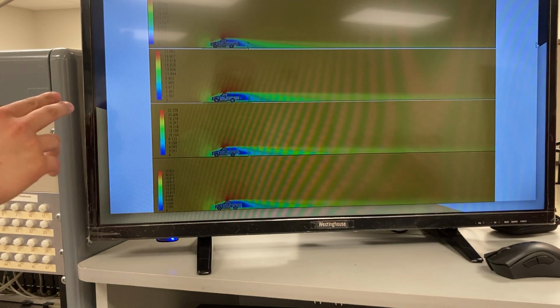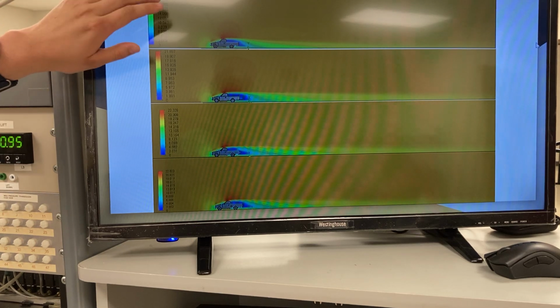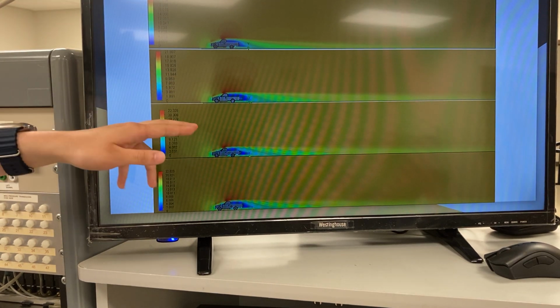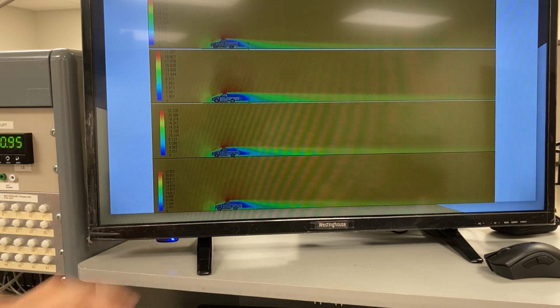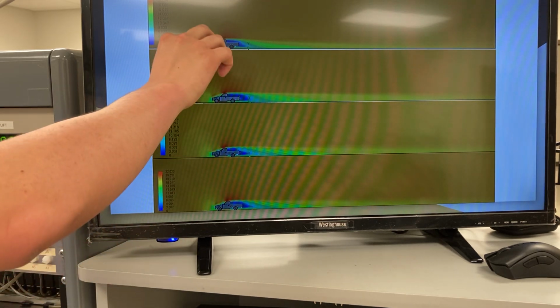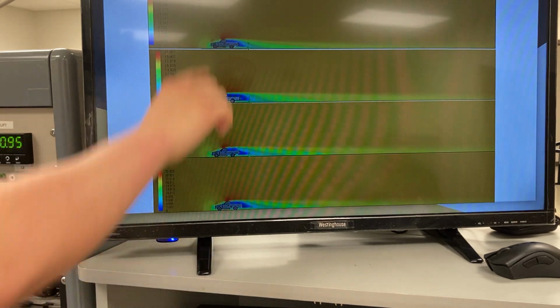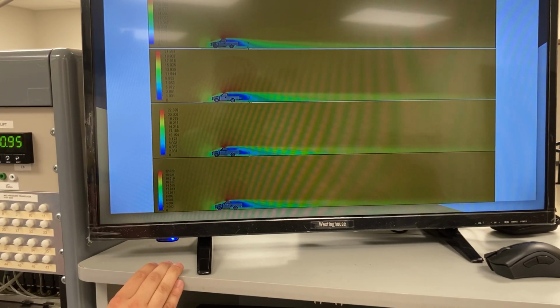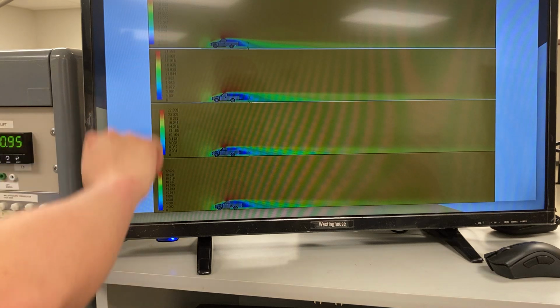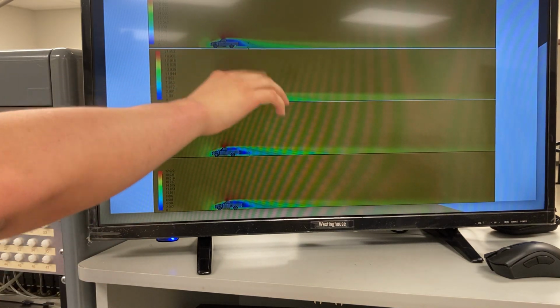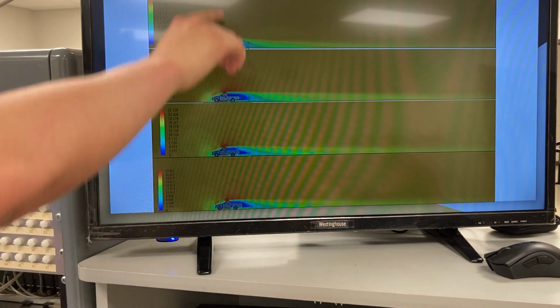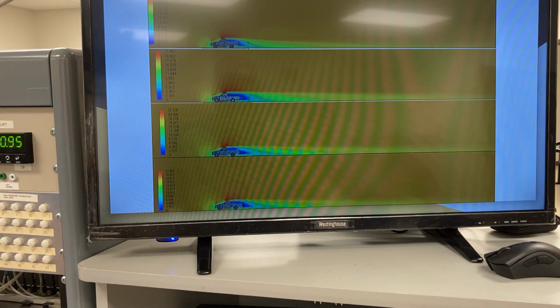And here are wind velocity contours. So on the top here is tailgate up, tailgate down, tonneau cover with the air scoops. And so of course we know that right in front of the truck for all these will be the stagnation points. Velocity will be equal to 0 at that point. And a thing to take note of is the velocity profile right behind the truck and along the bed.